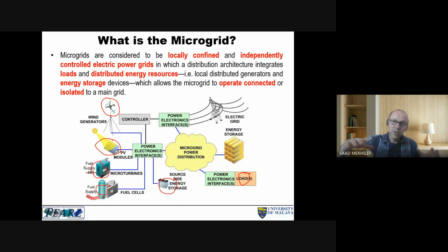Sometimes you have the volume, the Q. So the micro hydro depends on two factors, which we call the head, which is the height, and the Q, the amount of water. So it depends on the resources, but it can range from a few kilowatts to megawatts.